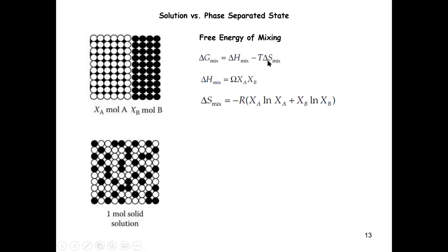And then we can take what we already derived for the ideal solution for the entropy of mixing. Again, assuming that the system does not quite distinguish different states according to their actual energy. Okay, but this is a big assumption. But anyway, we have already used it, so these are consistent, right? Because when we derived this enthalpy of mixing, we used the same assumption.